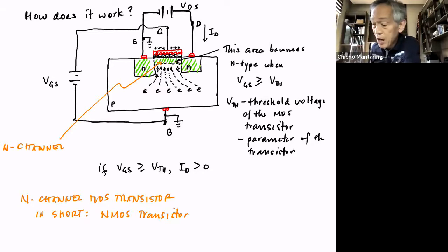So that's how the MOS transistor works. Without any VGS, current cannot flow. Current cannot flow here because you have two back-to-back diodes in effect between this N, the bulk, and this N. But when you apply a VGS, if that VGS is greater than a particular threshold voltage VTH, you are going to enhance this particular area. That's the technical term. It's an enhanced channel. You're going to enhance a channel into this particular area. So this is going to be a continuous N section, and now current will be able to flow.